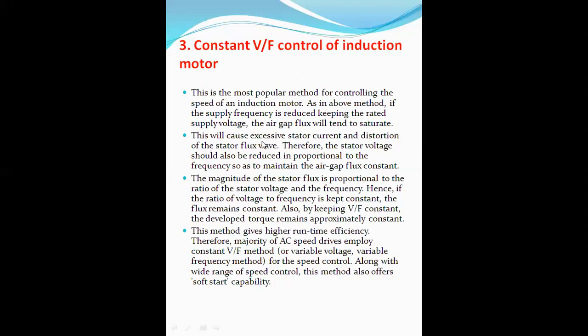This will cause excessive stator current and distortion of the stator flux wave. Therefore, the stator voltage should be reduced in proportion to the frequency, so as to maintain the air gap flux constant. The magnitude of the stator flux is proportional to the ratio of the stator voltage and the frequency. Hence, if the ratio of voltage to frequency is kept constant, the flux remains constant.